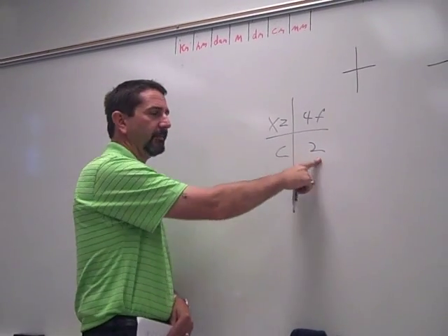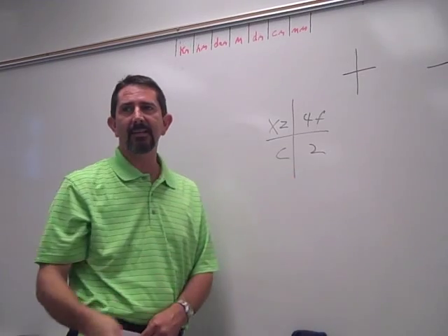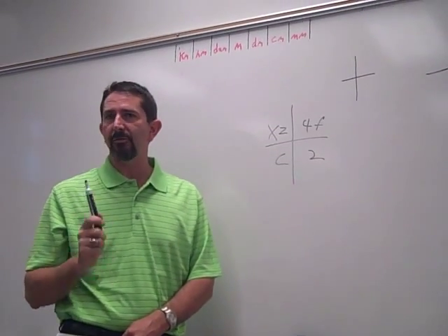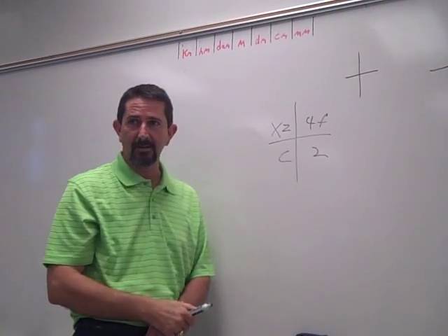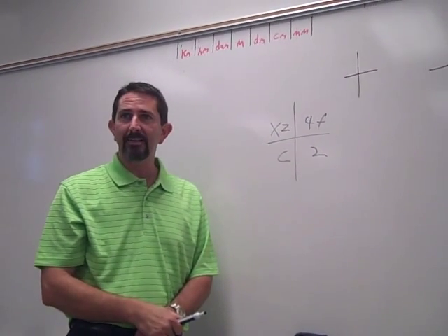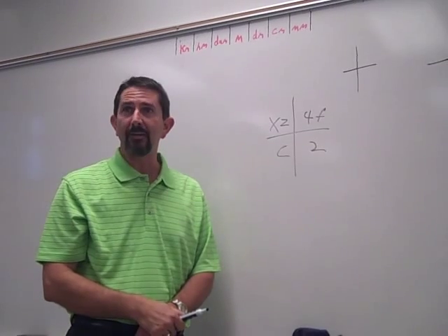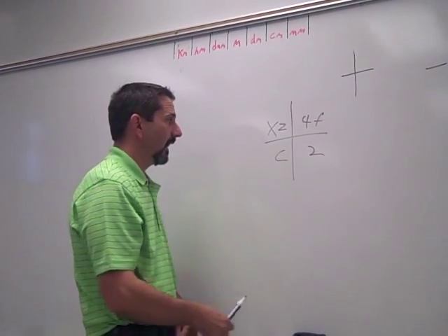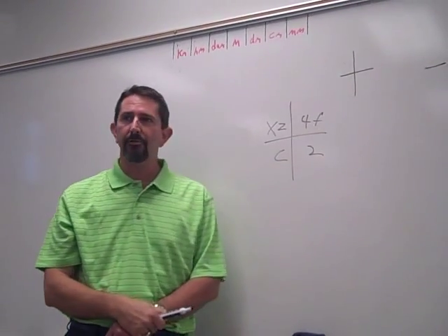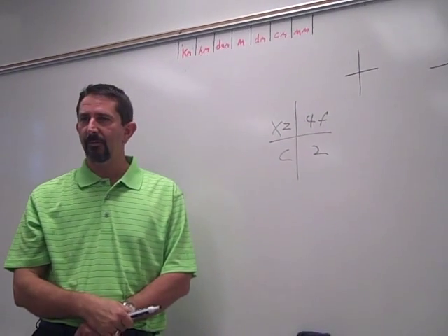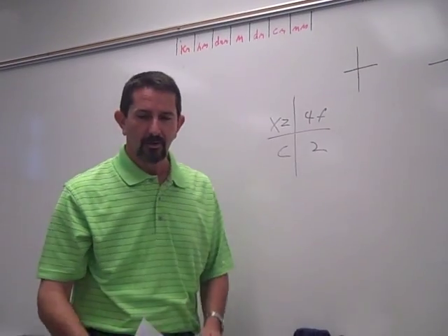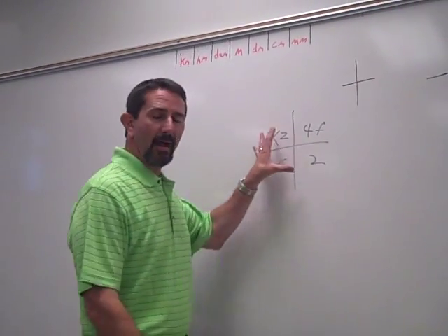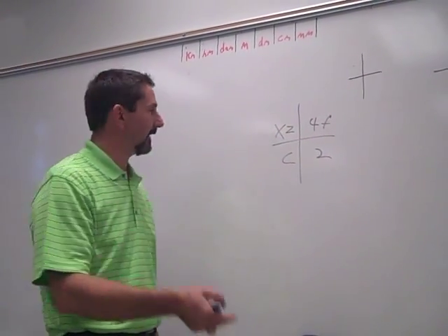The next quadrant is the length in 16ths. Driven fasteners generally do not have the length given. I put it up here just for the sake of this example. Usually you only see length given for mechanical fasteners. Okay? And then the final quadrant is hole preparation. This one is C for countersunk. Okay? So I can tell you everything I need to know about the fastener that's going to go in here just by looking at this.